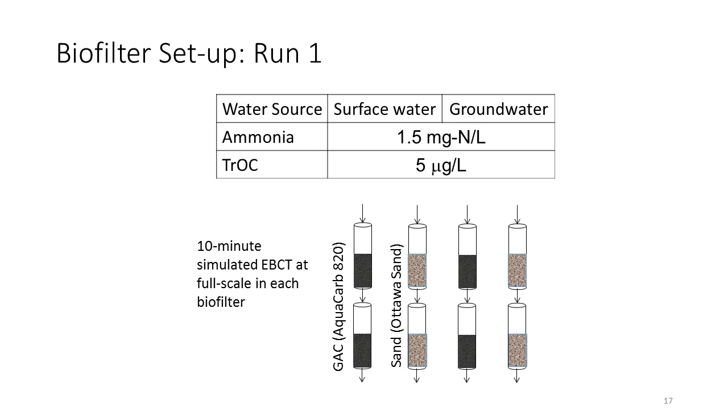And each of these biofilters, you'll keep seeing throughout the presentation that I'm saying 10-minute simulated EBCT, or total 20 minutes simulated. So we used a scaling model to simulate what it would be at the full scale. So at bench scale, it's I think around 3 minutes, and then at full scale, it should simulate about a 10-minute EBCT for each of the biofilters.